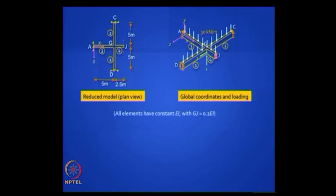So D1 and D2 are the only displacement unknowns. Then at the restraint coordinates, of course, you can add all the remaining degrees of freedom. So you have altogether 10 degrees of freedom, 2 of which are active and 8 of which are restrained. Is it clear? I am just demonstrating with one example.